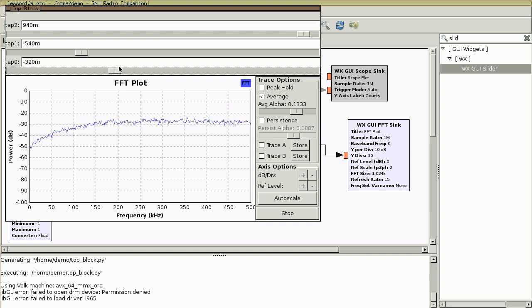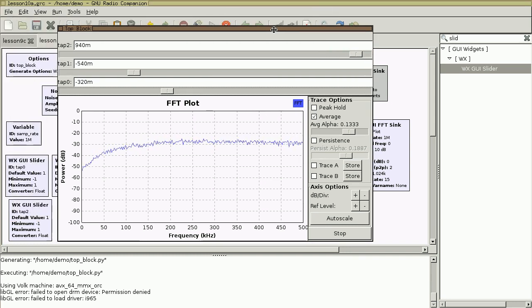Look at that. I can even create a high pass filter. Just by fiddling with these sliders randomly, I found that I can create a high pass filter instead of a low pass filter. And all we're doing is making a moving average that is weighted, and I'm changing the weighting. And those values, those coefficients of the weighting, I call taps.